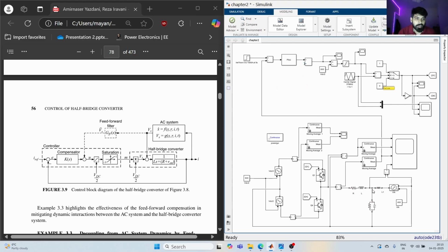We'll give the information at this node, which is basically the source as seen by our converter system. So by calculating the voltage here, taking into account all these characteristics L, R, C and everything, and writing the equation for the Vs here, which has a dependency on current, we'll try to form the equation.